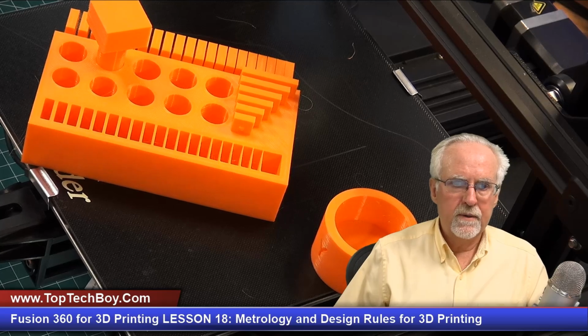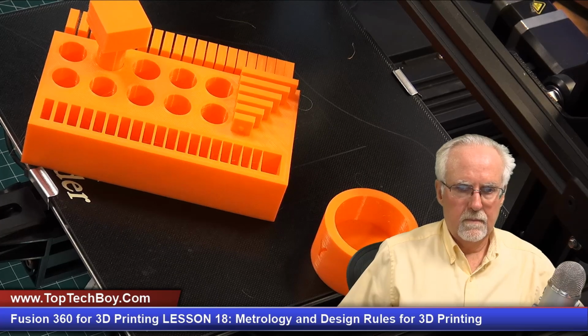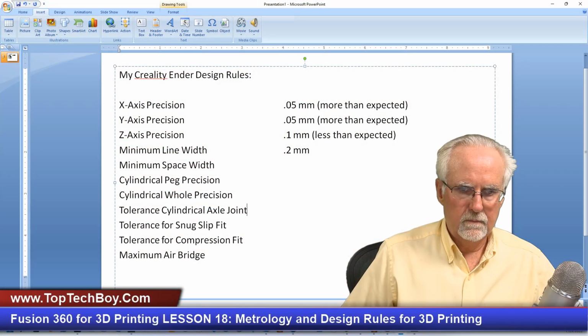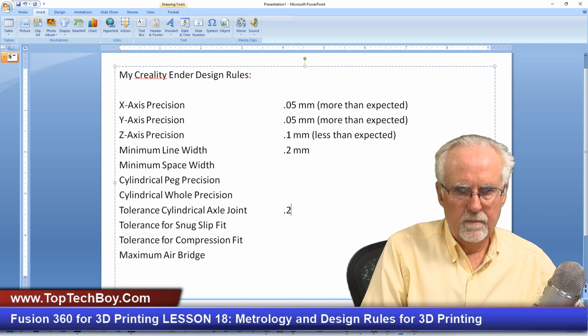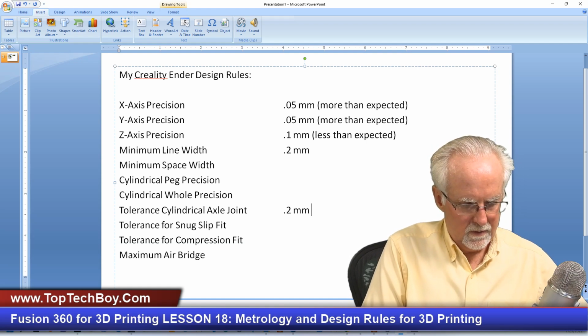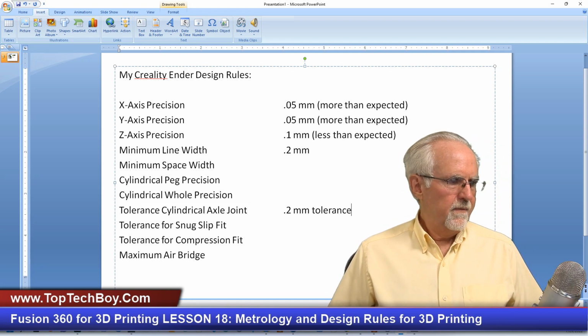I'm going to want this tolerance down here, 0.2 millimeters. And we did the minimum line width that we can do is 0.2 millimeters. And then we say that for our cylindrical axle joint, we want a 0.2 millimeter tolerance. Okay. And let's see if we can understand that tolerance a little better.